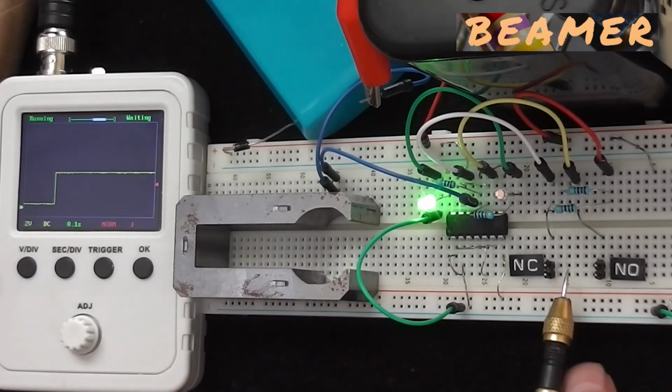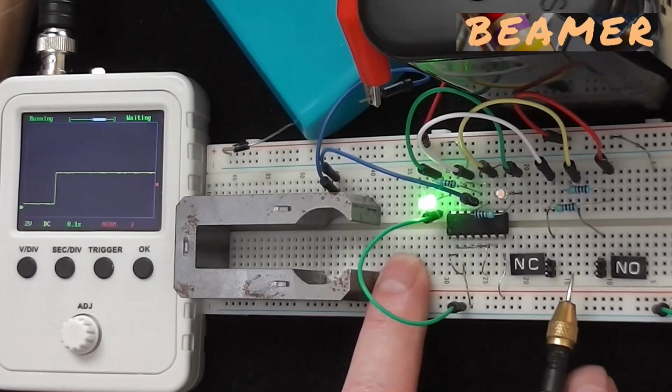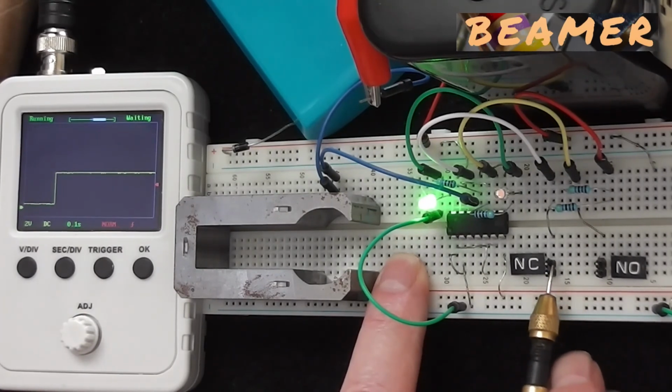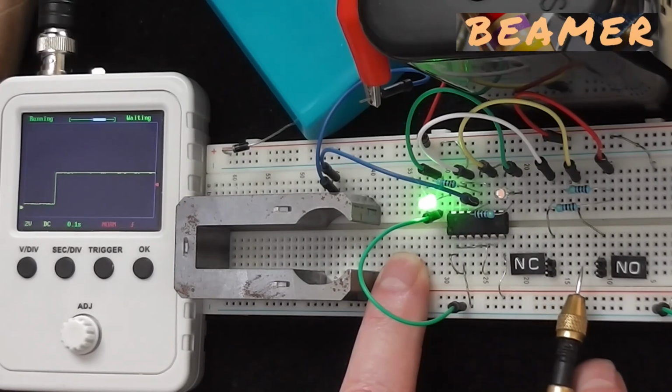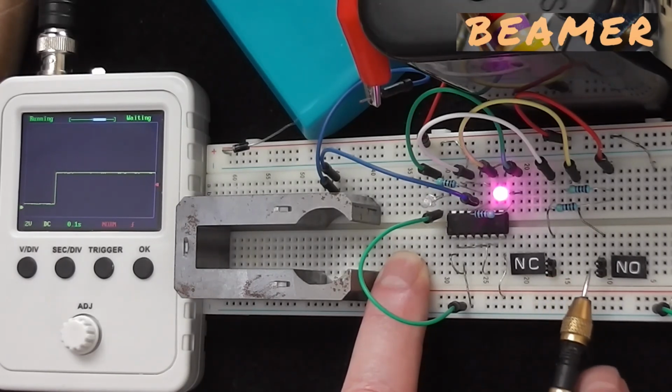And as you can see on the waveform there, the state of change is very clean. There are no additional pulses. And what I'll do, just to emphasize that, is I'll go back. So if the wiper is touching now the normally closed contact, it will take the micro switch wiper completely moving back over to the normally open contact and operating that before it resets the flip-flop. And there we are. That's basically how the operation works.